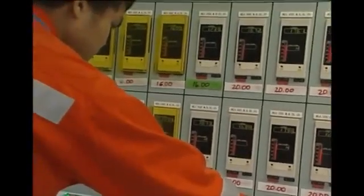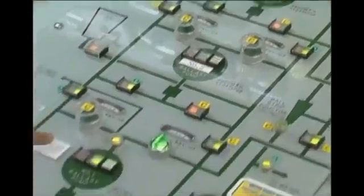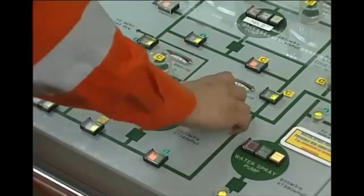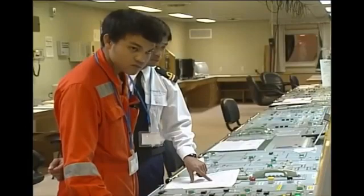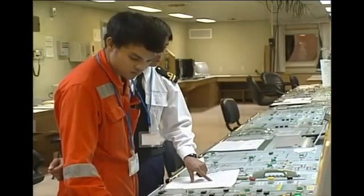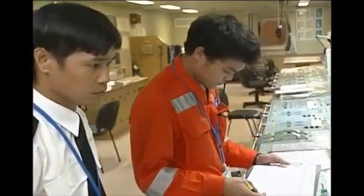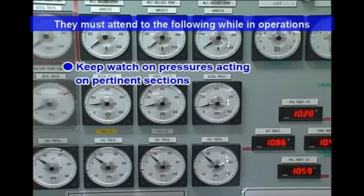Officers and crew responsible for ballast operations must fully understand their ballast pump characteristics, ballast tanks and lines, valve arrangement, and other facilities. Especially, they must attend to the following while in operation. Keep watch on pressures acting on pertinent sections.